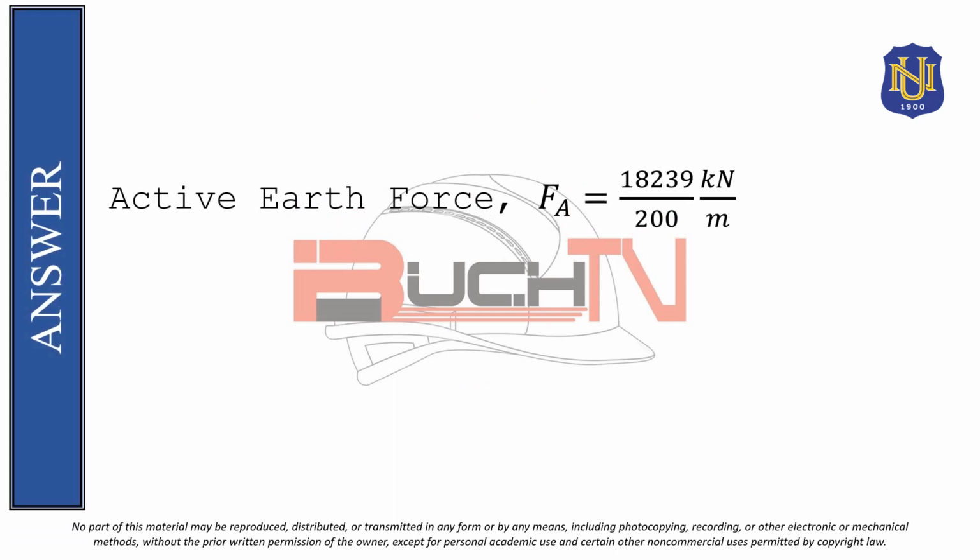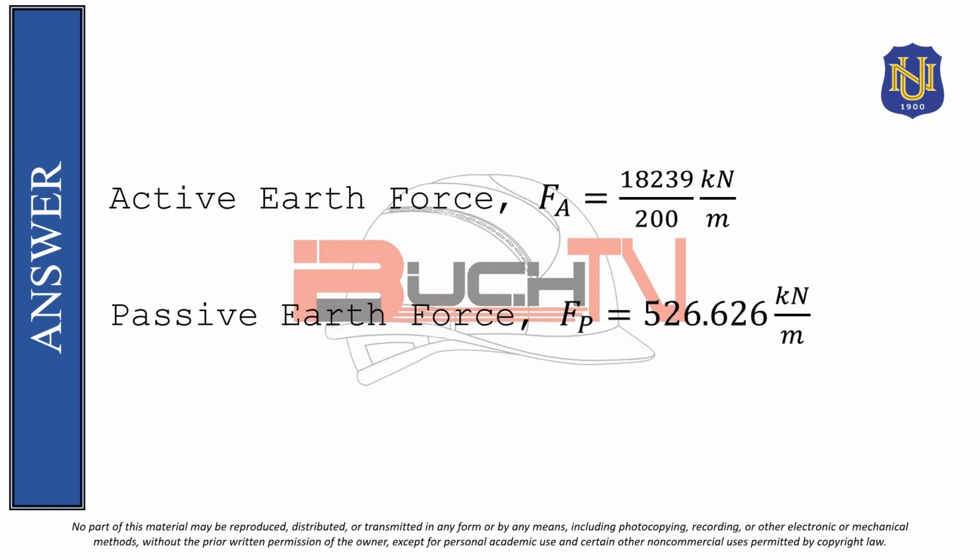So, for the answer, for the active earth force, we will have F sub A is equal to 182.39 kilonewton per meter, and for the passive earth force F sub P, that will be 562.626 kilonewton per meter.